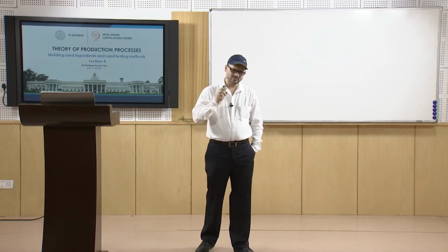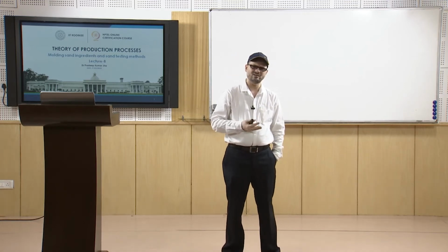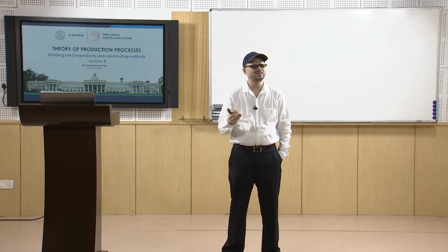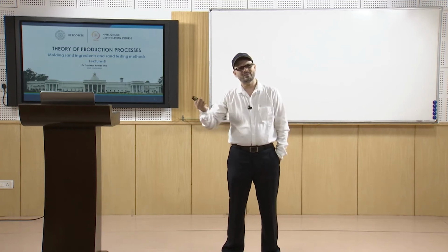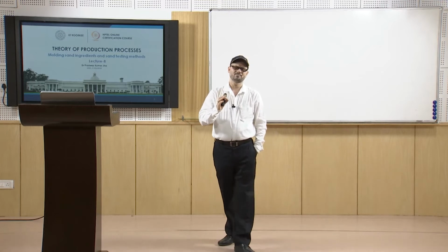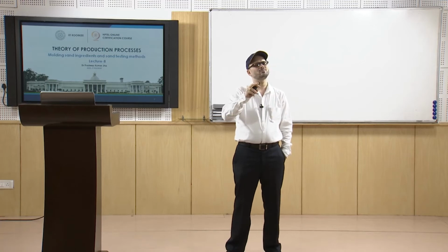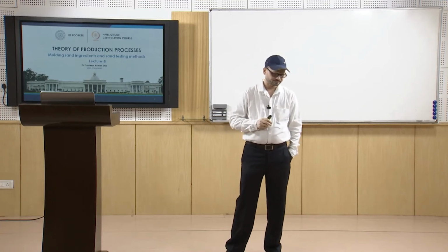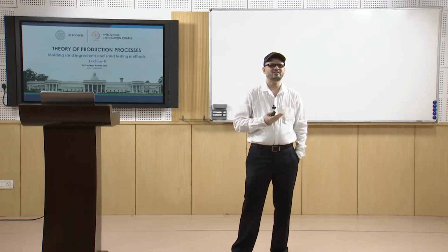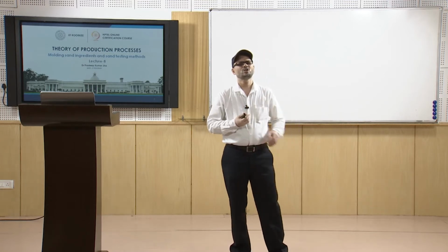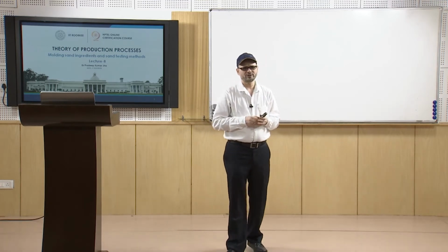So, the sand must have the refractoriness property. The sands we are using, like silica sand, and we are going to discuss the different kinds, such as silica sand, zircon sand, olivine sand, can withstand high temperature. That is why they are suitable to be used as molding sand. Then green strength, dry strength, hot strength are about the strength to sustain itself against different forces, its own weight or shape.